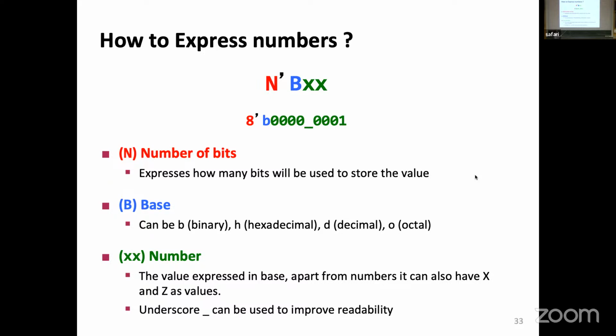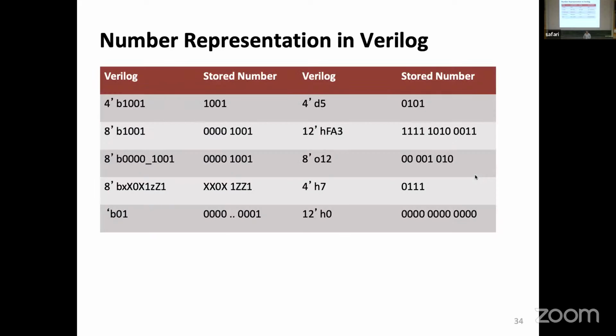If you are defining them in binary format and you're saying, this is a bunch of zeros and ones, they are a bunch of zeros and ones. If you're writing a hex number, it's a hex number. Decimals will work, sort of, but you have to be careful. Generally, just think that we are trying to define a sequence of digits. Now, here are some examples, and let's see what happens. Be careful again: Verilog will not complain when you do funny things.